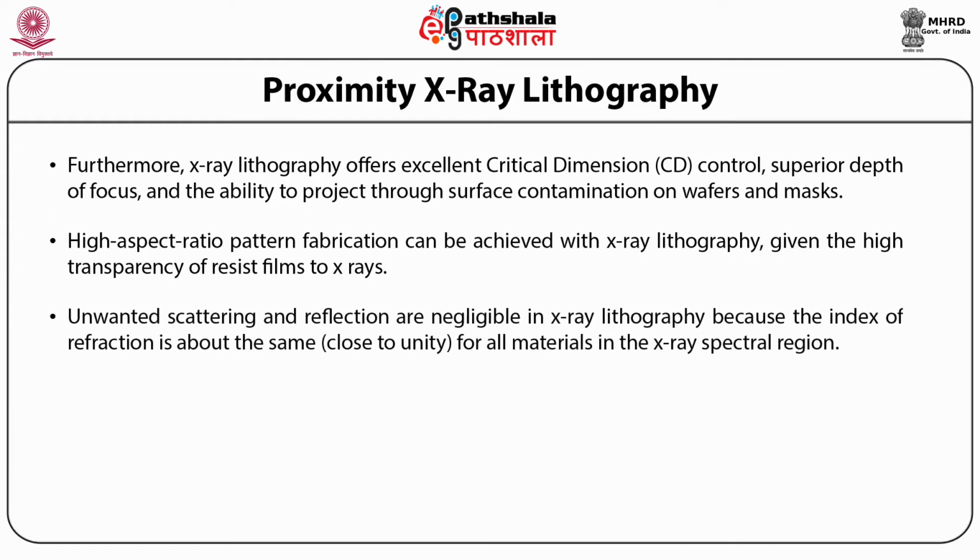Another advantage of X-ray lithography is the negligible unwanted scattering and reflection, which is due to the fact that the index of refraction is almost the same, close to unity, for all the materials in the X-ray spectral region.